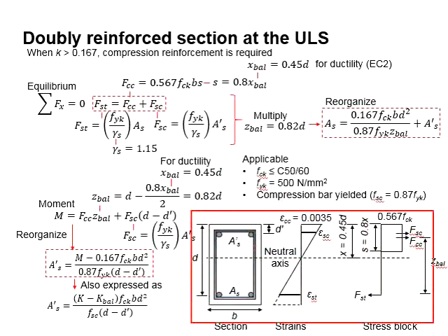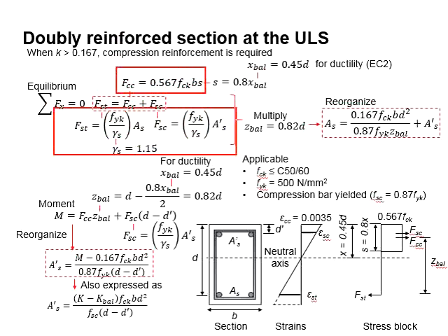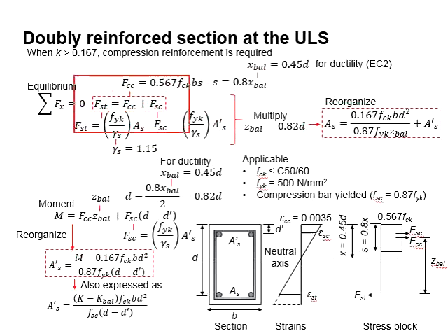From the stress plot diagram here, we will determine the equations based on the equilibrium equation. In the case that sigma Fx is equal to 0, the tensile force in the steel bar will be equal to the summation of the compressive forces in the steel and the concrete, as represented by this equation. Assuming both the steel bars in compression and tension yield at the same time, and the concrete is at its limit together with the yielding of the reinforcement bar, the equations are given here.